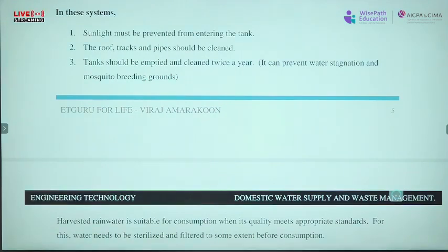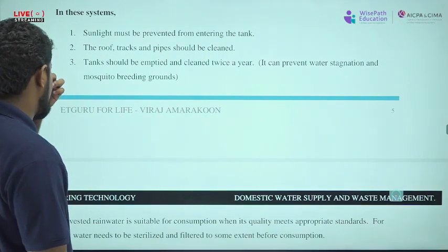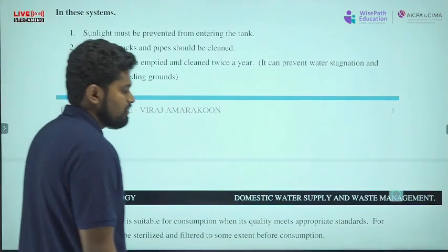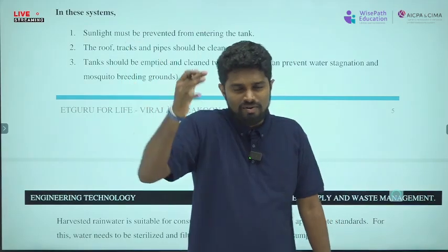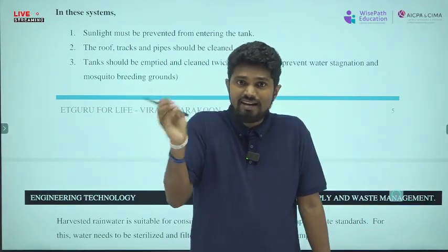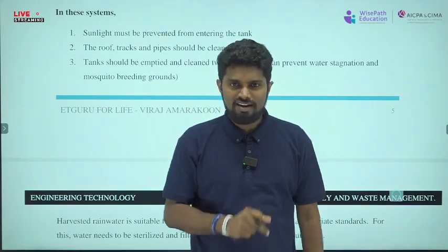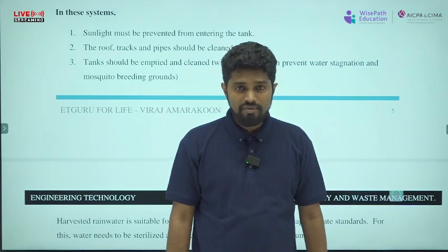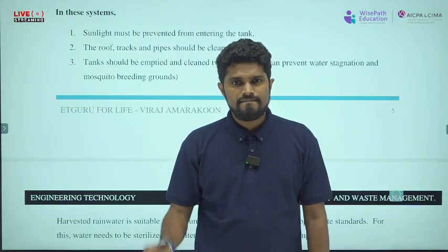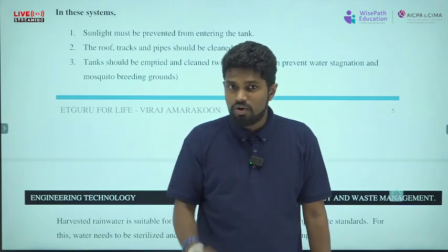And the roof, gutters and pipes should be clean. There is a plumbing system, no? There is a drainage system. You have to clean that system. First reason is it can get blocked. And also, to prevent dengue. Because if it blocks, water gets stored there.